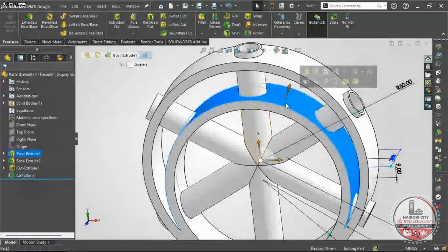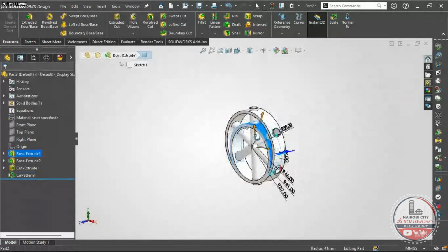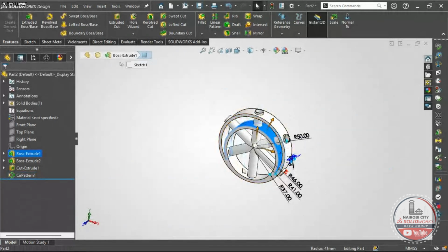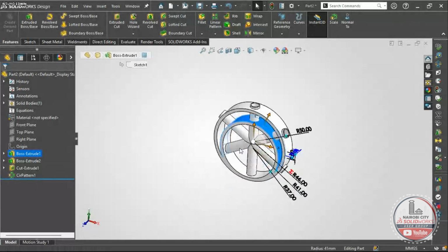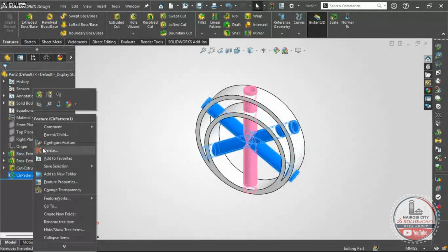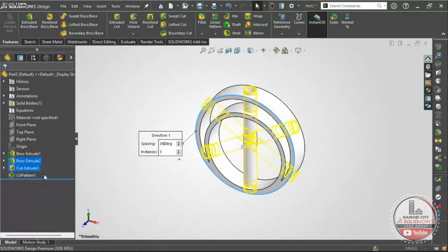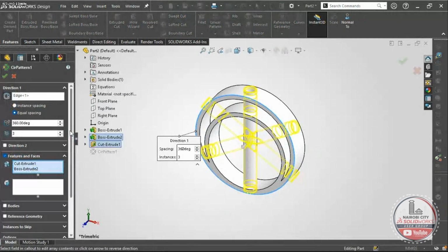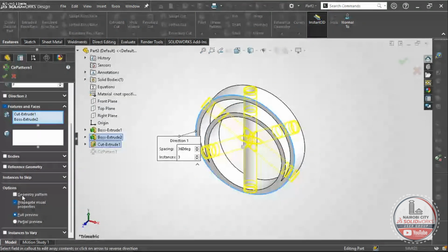The reason it was refusing with the geometry pattern being considered is that this is a sketch. It is not for one. It is not within the same. The outer circulars, they are not concentric. So you have to consider that option. In most cases, when you come to circular pattern and it refuses, you have to play with other options here. Geometry pattern is also another factor to consider.